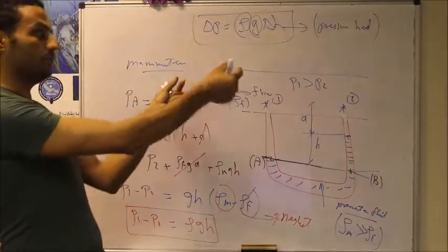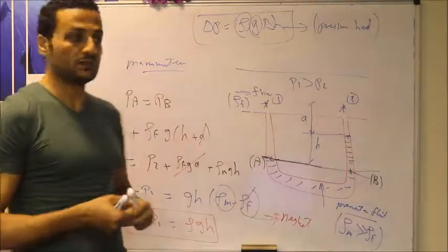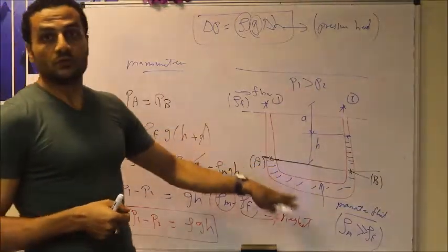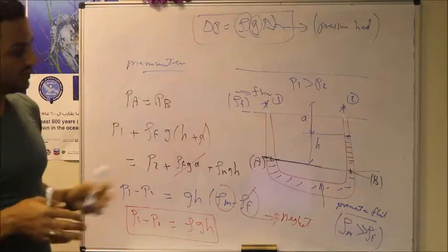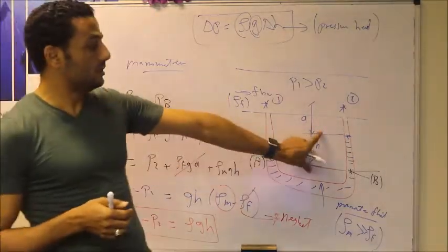We can just make two openings between the two points that we want to measure the pressure difference between. Put in manometer fluid with a density a little higher or much higher than the density of the flowing fluid. At steady state we have a height difference.